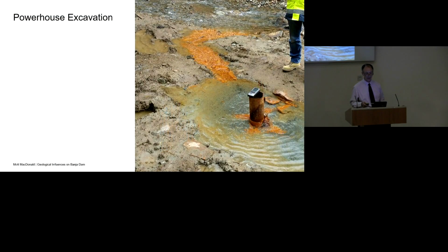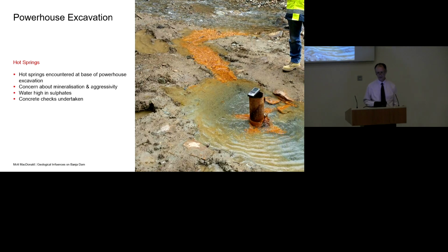One other little anecdote was that in the powerhouse excavation, we ended up with some hot springs. Some hot water appeared right at the bottom of it, and it was rather sulphurous and foul-smelling. And there was some concern about mineralisation and aggressivity to concrete and so on, and it was found to be high in sulphates. So checks were undertaken to make sure the concrete would be adequately protected.